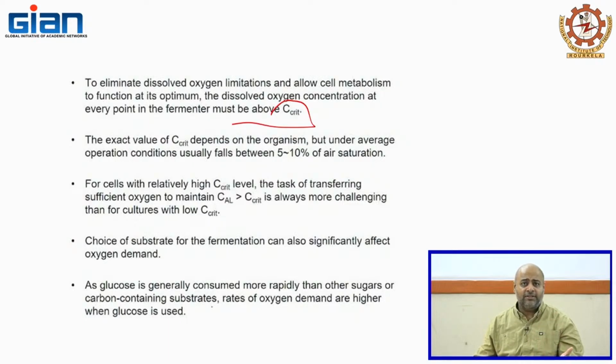Through experimentation. You will try to see the optimum growth, right? You never go to the fermenter directly, you always go to the seed culture. You have a small scale fermentation unit first, that is what you are trying to optimize, and only then you go into the industrial scale fermenter. So you try everything there, understanding the relationship between all the process parameters and your cell growth, and only then you replicate that in a large scale fermenter.